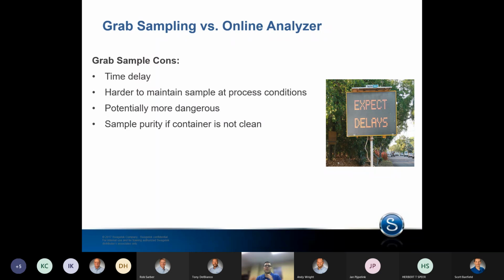And the purity in representative sample collection could be an issue if you're not properly maintaining your stream of sample bottles, purging them, cleaning them down before you put them back into the panel system, because that contamination can just flush through and ultimately affect your readouts when you take the next sample to the lab.